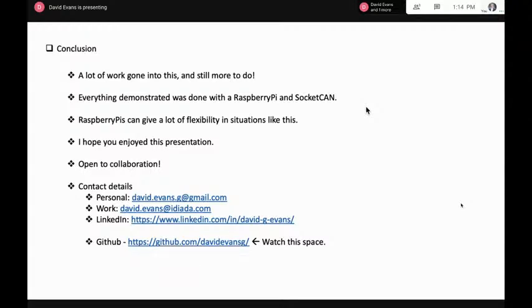So in the end, I had 3 Raspberry Pis with those 3 shields, sending real CAN messages onto a bus, and I was just generating some traffic. More specifically, it was traffic I was in control of, or traffic I understood. So I had a simulation tool feeding the Raspberry Pi's data. The Raspberry Pi would just generate specific messages based on the data, and populate the bus to try to reflect a real vehicle. It only had about 30% bus load, which wasn't much, I guess, but it was enough to let me do what I wanted.